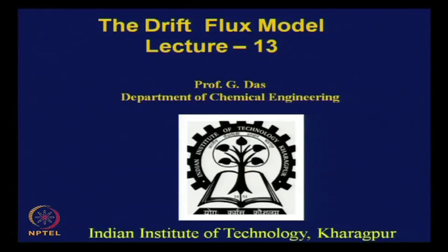Okay. So, till now whatever we had done, we had discussed the different analytical models, and I had told you that there are usually two extreme situations. One is the homogeneous flow model, where we consider that the two fluids are intimately mixed with one another, and we assume it to be a pseudo fluid with suitable average properties. The next extreme is we assume that the two fluids are completely separated. They may interact, they may not interact at the interface. If you assume that they do not interact at the interface, it is a gross assumption. At times we do it to simplify calculations. Okay. The other extreme is the separated flow model.